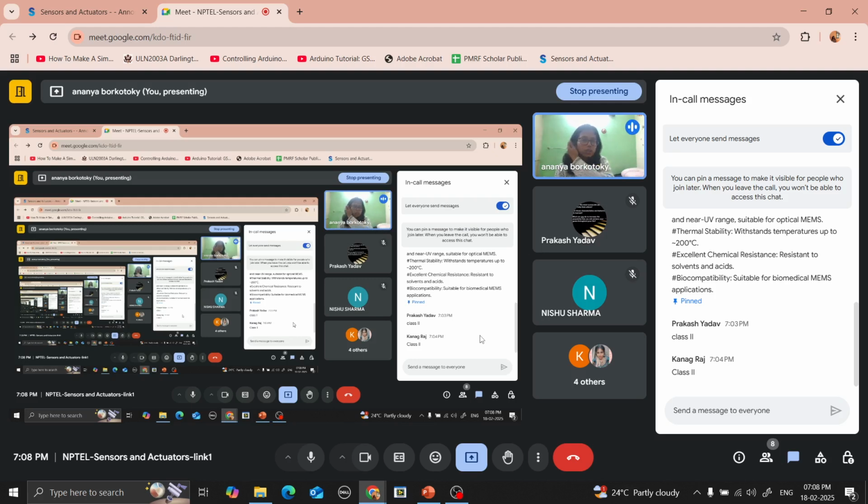In the case of class 2 and 3, it also filters the air before entering the hood, so that actually protects the product as well. The difference lies in the different subcategories. Some portion of the air is recirculated inside the hood, and some portion is released after filtration, and based on how much is recirculated and how much is filtered and exhausted, other categories are defined.